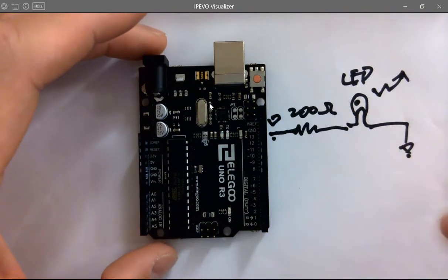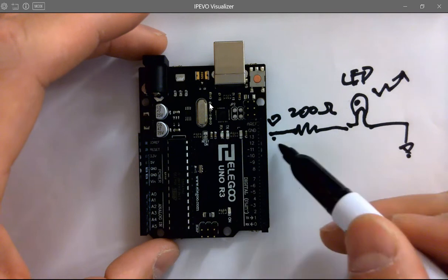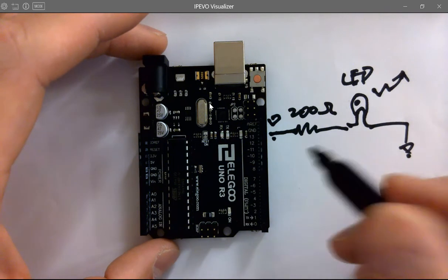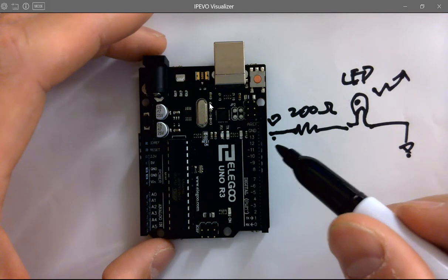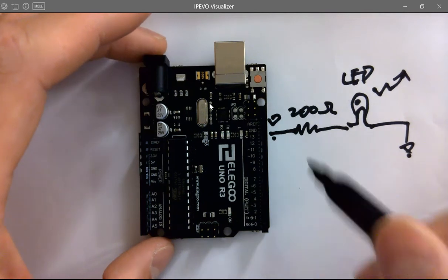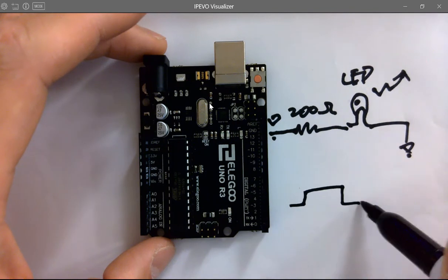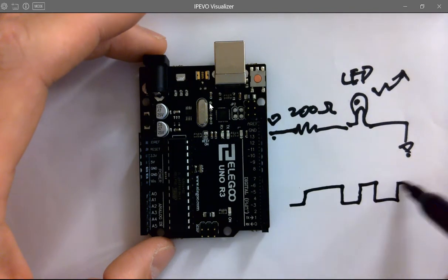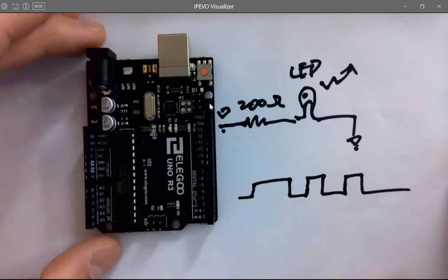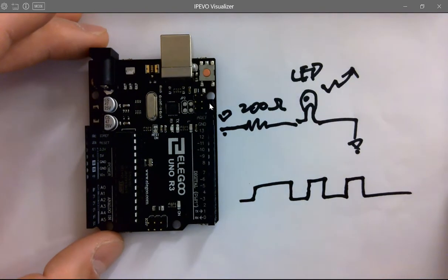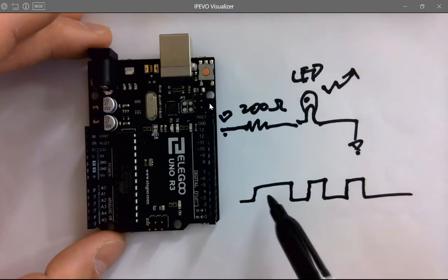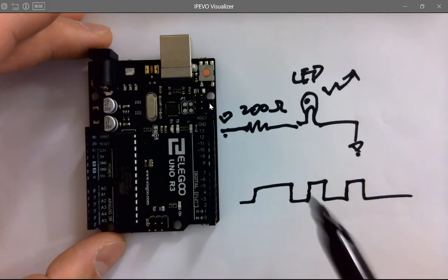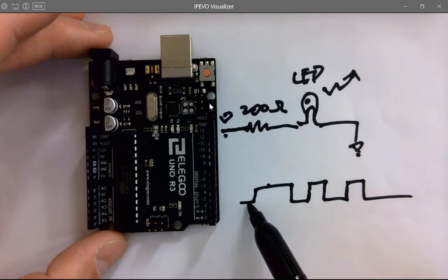The main principle of using microcontrollers to control digital systems is literally just flipping the pins. If you flip or toggle them really quickly, you can create different sequences of digital outputs according to the timing diagram of the sensor or anything, so you're able to communicate with digital systems. It's very sweet and repeatable because digital is way more reliable compared to analog signals. If it's 1, it's just 1. If it's 0, it's just 0.